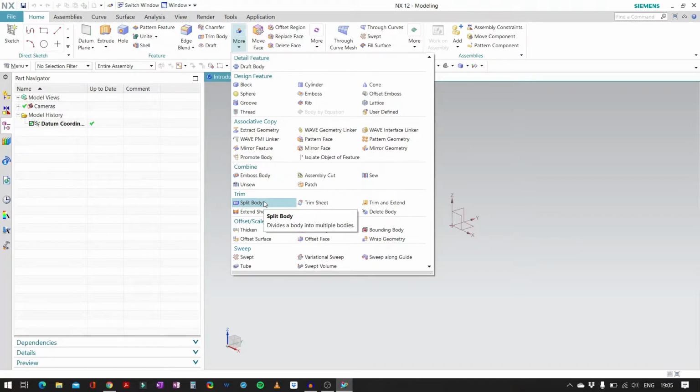I need a single body, or for the sake of meshing, I need two separate bodies, not dividing the surface, but two separate bodies which I will mesh, and which I'll import into some FEA application like ANSYS in APDL or Workbench, and then I'll work upon it. That's my requirement. I can do it here.